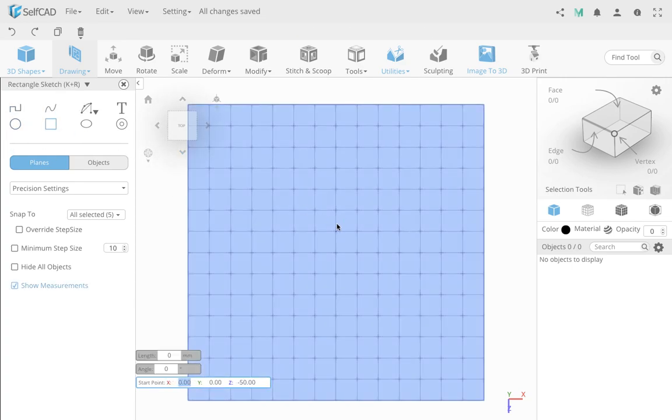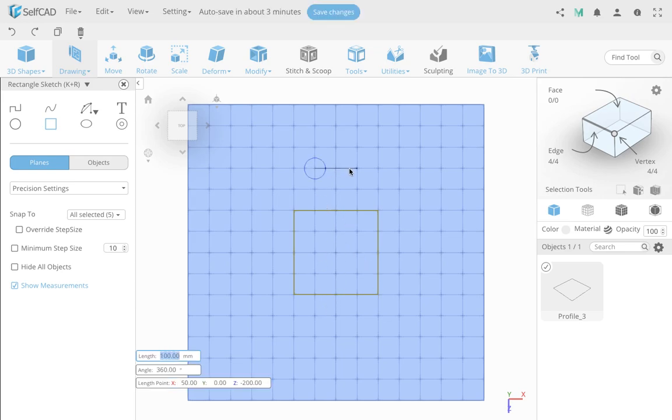And I'm going to create a very basic drawing here. Here's the center of the object. I'm walking up by 2, I'm walking out by 2, and you can see it snaps. Now I'm walking out 2 and 2 again, and I can bring it down 4. So we kind of have just a nice rectangle. Now we're going to go up over here by 2, and I'm going to bring it down to snap on this.